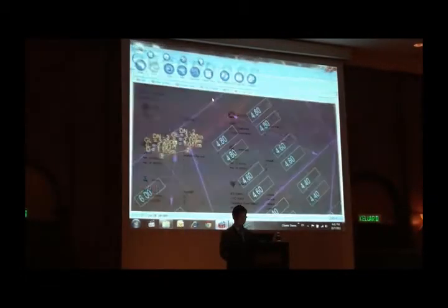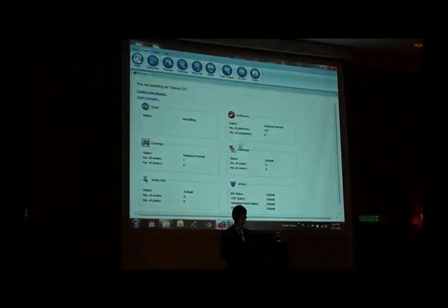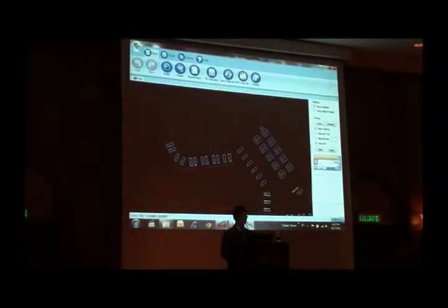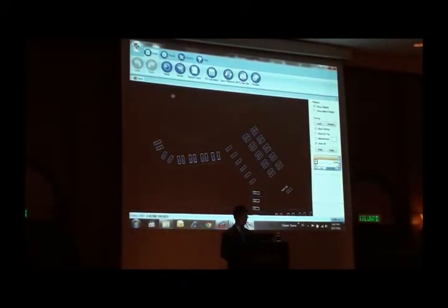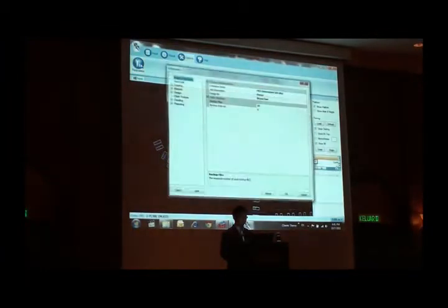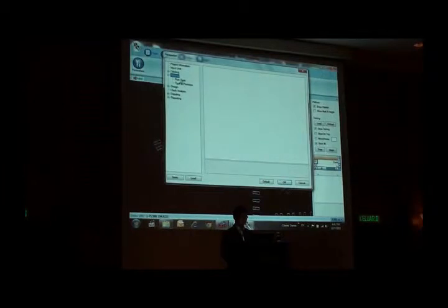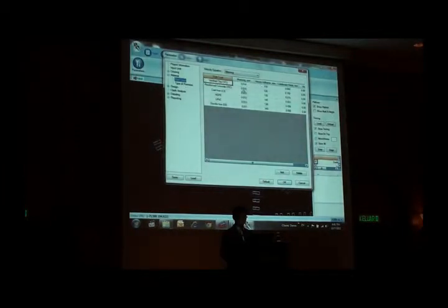So we can turn off and go to the next module. It's inside the same software, so we can see it's still the same. The network, everything is still the same. We can do some editing in the parameter setting also. For the material, we have this pipe type. This is the default setting. We have 6 types: VC, RC, CI, HDPE, UPVC, and DI. We can add more.